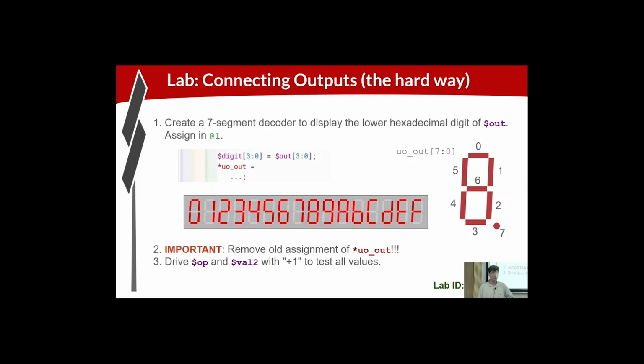All clear? Any questions about driving the +1? Yeah. So the goal here is just to test that all of the bits that you've defined are correct, that each case is driving the right bit pattern to represent the number the way that you expect, right? Very easily you make a mistake and accidentally drive a 0 for this segment of the 9, right? It's going to show up goofy.